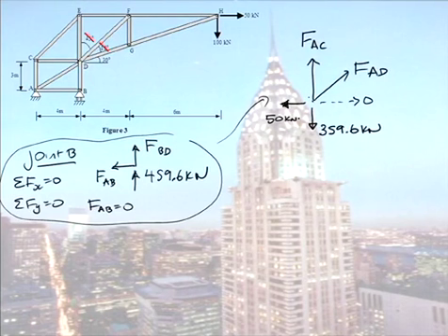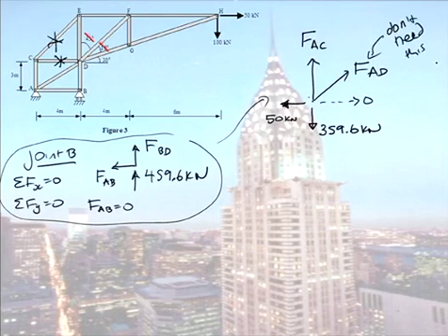So when you draw your joint, ask, is this a pin joint? It has to have 2 reaction forces. Not even 10%, maybe 15% of people would have forgotten to put that 50 there. So anyway, once again, the forces we're interested in are that force and this force. So you can see we don't even need this. Well, you do in this case, because you need that to calculate the other one, but check what you require and work through it.